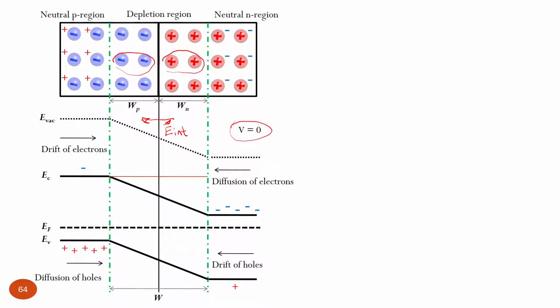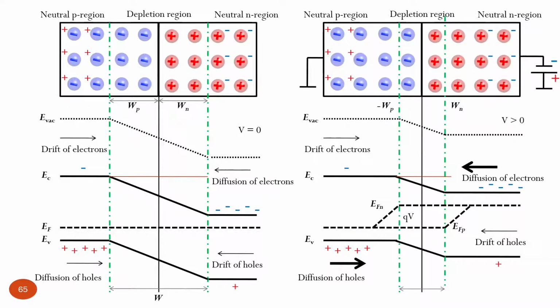If we want to make a forward bias, we need to be sure that external electric field is in opposite direction. When will this be in opposite direction? So we attach minus to n-type and plus to p-type. So that's, I believe, a very straightforward way to consider which polarity will be the forward or reverse polarity for a given p-n junction.